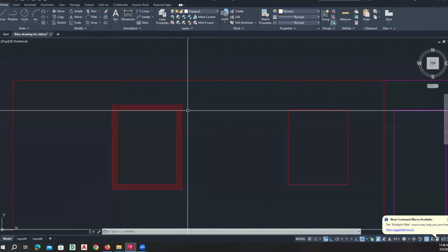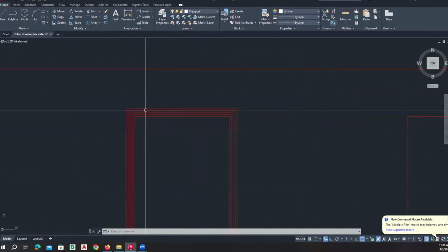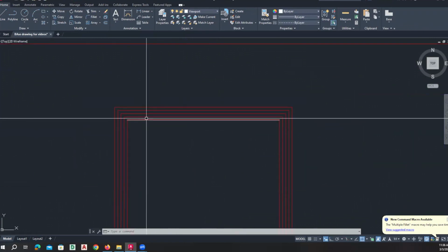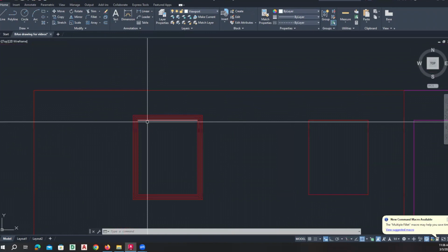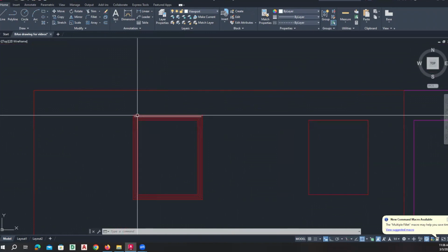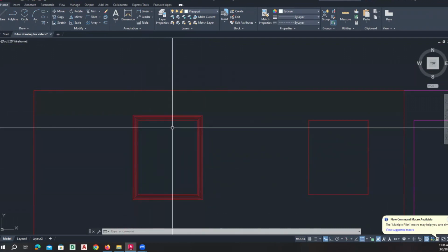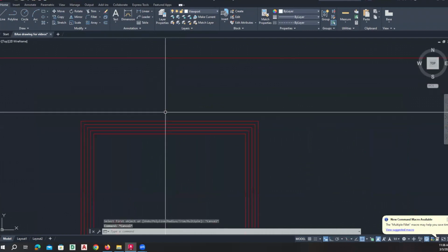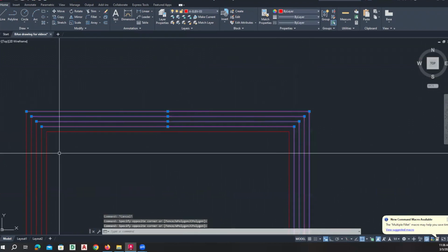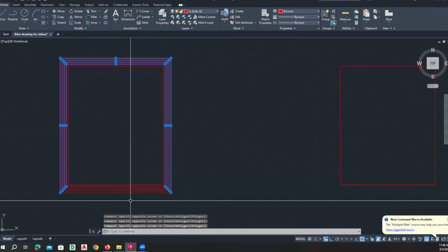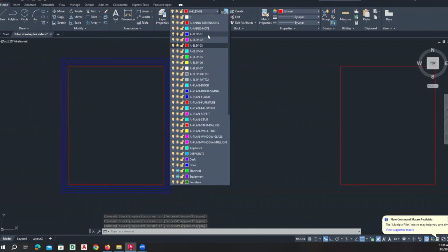However, what I want everyone to do is when you're printing this, make sure you observe the line weights, because when you have too many lines close together and they're on a layer that will print dark, these lines together will end up showing as if it's one big solid black line going across this window. And that will just look like a big blob, a big blur, right? So in cases like this, what I might do is actually take some of these lines like that and this and put those onto a lighter layer, let's say 0.01, right?